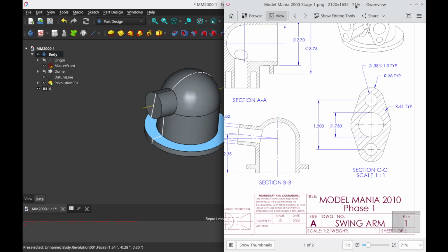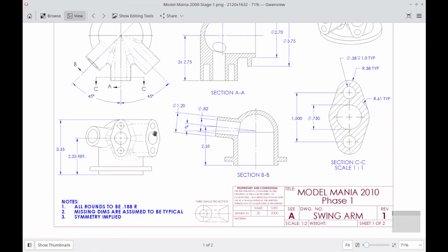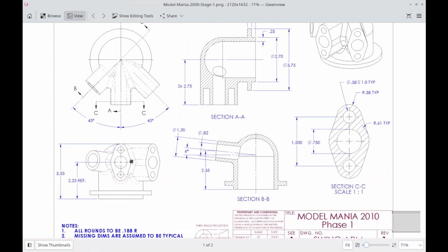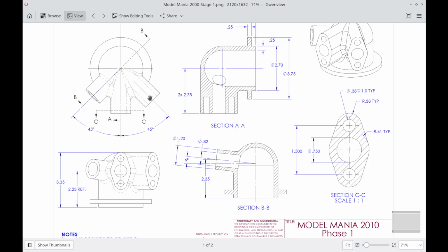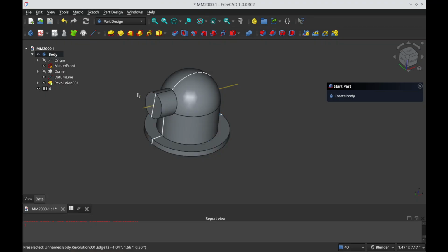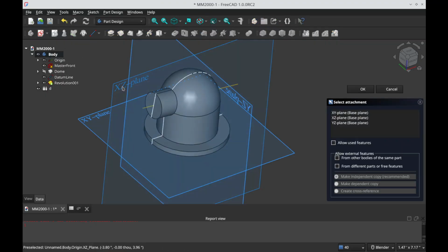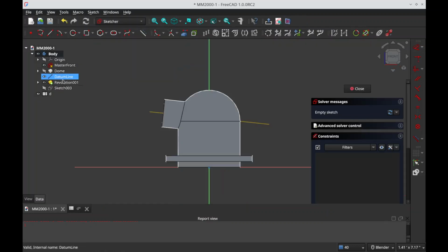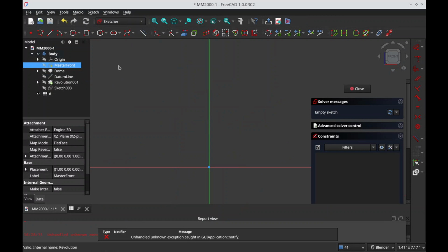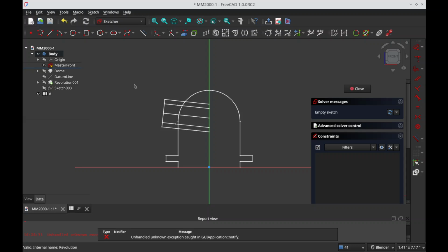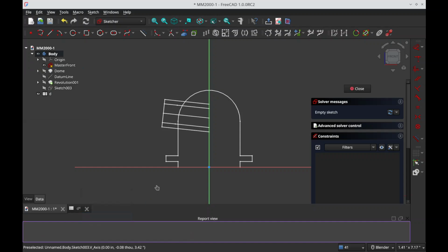So looking back at the drawing, we have one flange at 90 degrees to the pipe and one flange 45 degrees in the center. So we're actually just going to do a revolve with a few features to bring that in. So without further ado, let's sketch on the same plane, and this time we're just going to be drawing, so we can really hide everything that we've done so far, including the master sketch. Actually, we want to keep this top level dimension, and just clear that out. Start drawing this overall shape.